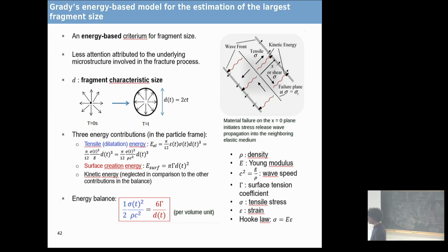Of course, there is kinetic energy, but it may be negligible. And that's why, for a long time, we made this error. We tried to make a balance between the surface energy and the kinetic one, built from the impinging velocity of the ice crystal. But it's not the right one, because this typical energy is quite negligible compared to the tensile one inside the ice crystal.